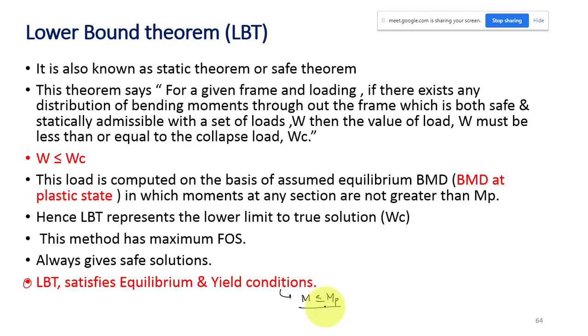And that is why, while applying this theorem, we will make use of the bending moment diagram. So we have a structure and we have some loading. You can use this theorem if you are able to draw your moment diagram. That means for simple structures like a single span simply supported beam or fixed beam, we can use this. But for complex structures, it is not possible to draw the moment diagram easily. To get the moment diagram is a tedious job. So it is applicable, but it will be difficult.